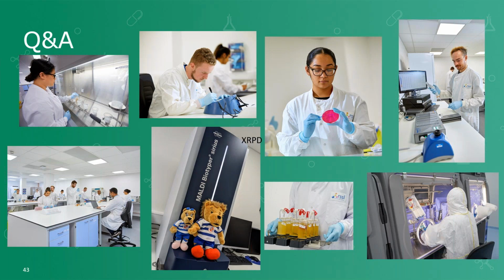There are different scales of that, but a lot of research has shown that a Reynolds number of 3,000 or more, whether that water is turbulent or laminar, is sufficient to keep the organisms in suspension and to create sufficient force to stop them adhering. Then the lower that number becomes, the easier it is for organisms to attach as they touch pipework.